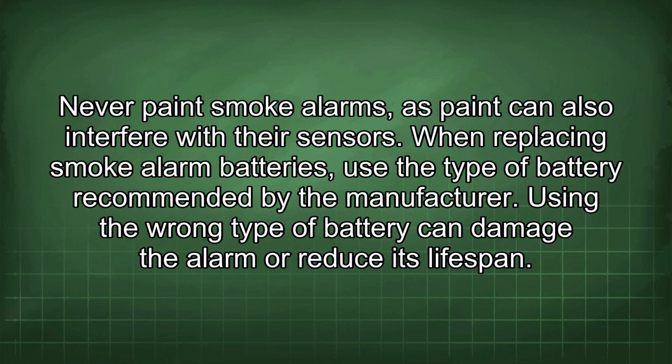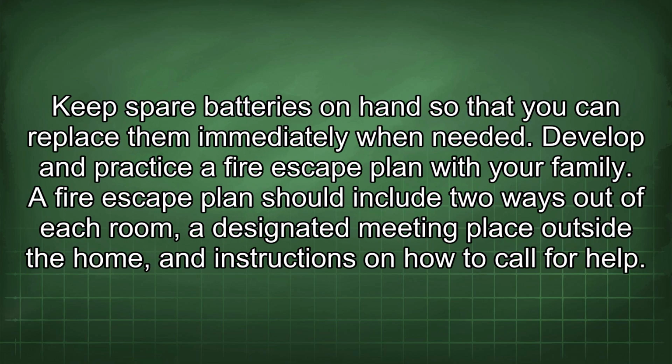When replacing smoke alarm batteries, use the type of battery recommended by the manufacturer. Using the wrong type of battery can damage the alarm or reduce its lifespan. Keep spare batteries on hand so that you can replace them immediately when needed.